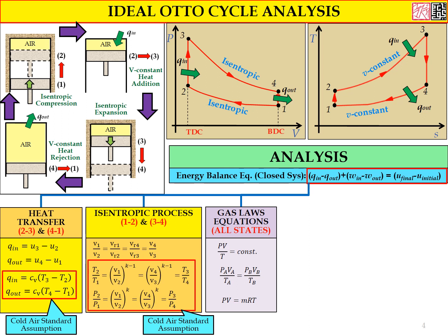P stands for pressure, capital V stands for volume, m stands for mass, R stands for the gas constant, normally given, and T represents the temperature. Okay, and you need to remember that for the gas law equation, the temperature must be in Kelvin.